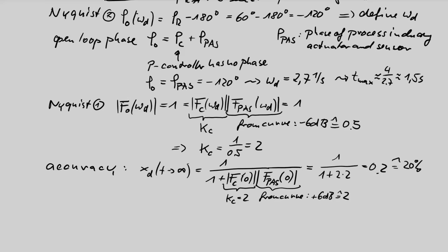We can say if you want to have a 1, we are 20% deeper. If you want to have 100 degrees centigrade, we get only 80. If you want to have 10 degrees centigrade, we get 8. So there is a constant, well-known error, but there is an error, a control error of exactly 20%. Okay, in the next video, this is video 50, in the next video I show you this system simulated with my program FRA C#.